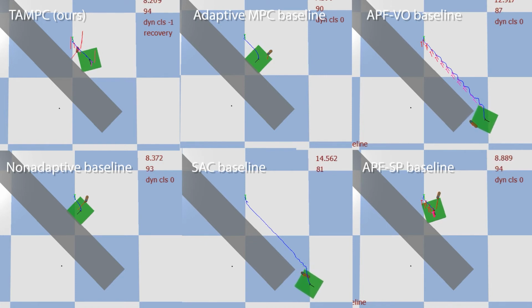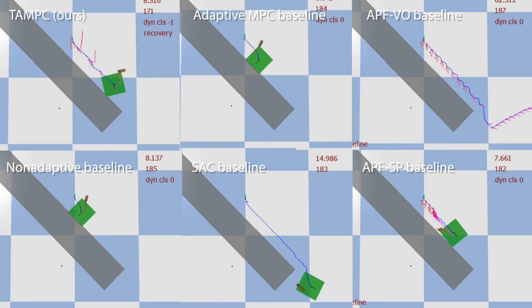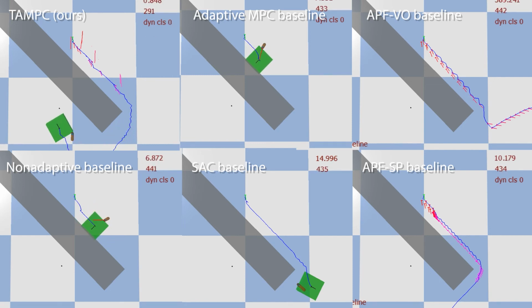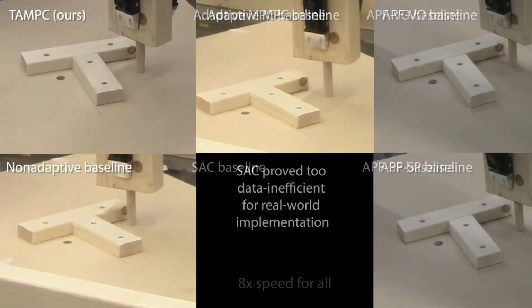At this point, the baselines are stuck in traps. SAC coincidentally outputs actions that keep the block parallel to the wall for out-of-distribution reaction forces on this task. SAC and the virtual obstacle baseline no longer make progress because the goal is behind the block, requiring a U-turn, which is a long action sequence that temporarily increases cost. Under these controllers, this is a trap. Our method continues down the hall while periodically entering new traps. These are unavoidable because we cannot anticipate them given limited sensing.